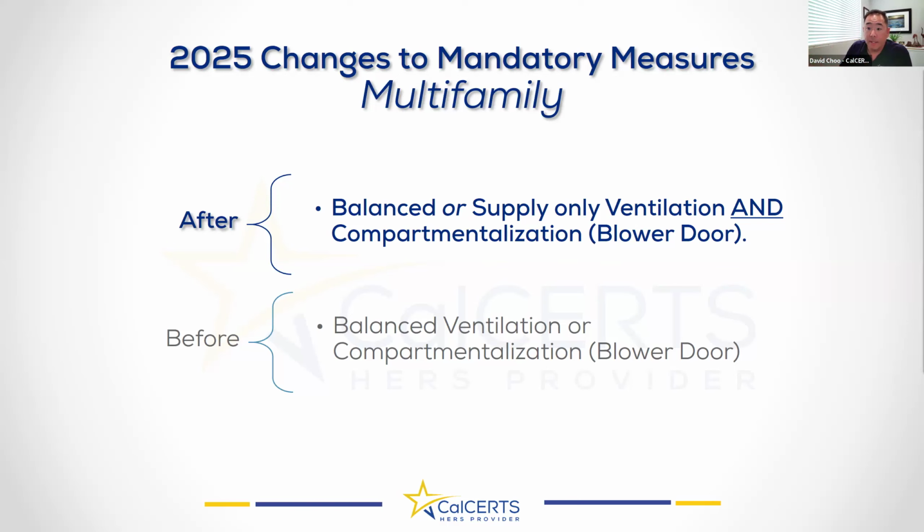Now, this upcoming code cycle proposal is that you can have balanced or supply ventilation, right? But the blower door is always going to be required. So whatever you do, the blower door is going to be required. So that's just going to be part of multifamily, the world of multifamily, compartmentalization, basically. And also, they got rid of exhaust-only ventilation in multifamily. So, the days of the fart fan being the ventilation are gone. Although you probably still want that in your bathroom. Yeah, you do.